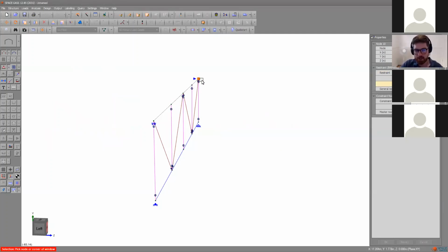So you're blocking the structure against movement. This way, that stops a rigid body rotation about X, and it also stops it having any movement in the Z-plane, which you don't want for a 2D problem. This one over here does the same, but it's added an additional torsion constraint, which again just helps the structure, remove some instabilities, but probably you don't need that for this question.